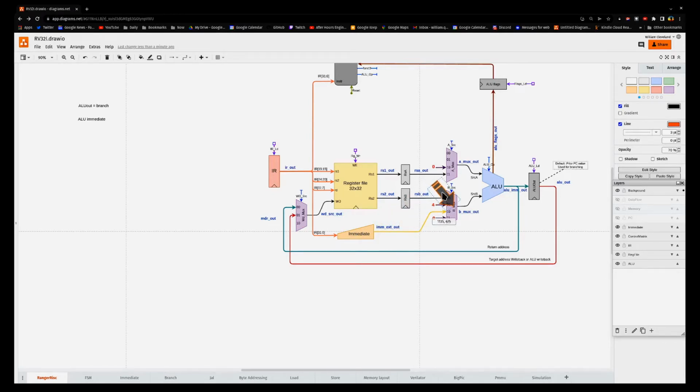So this all means that we need the control signals, the identical set of signals that we did with the R-type, but the signals will change. We still need the write back for the register. We need to select which source we're coming in from, the ALU out or the ALU register. We still need to select the appropriate RS1 output on this one, and we need to select the immediate on this channel right here.